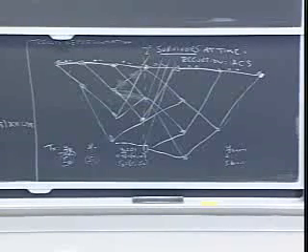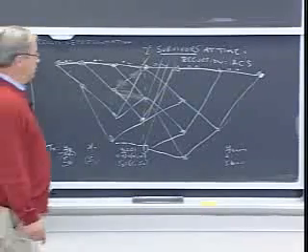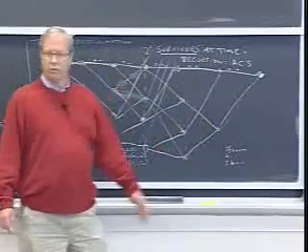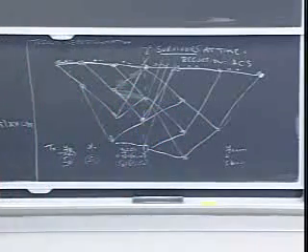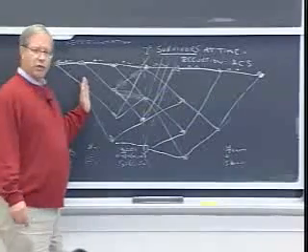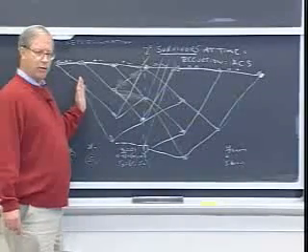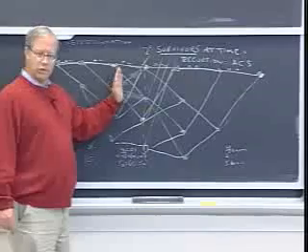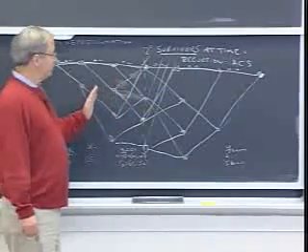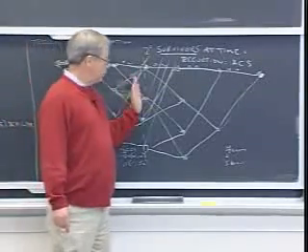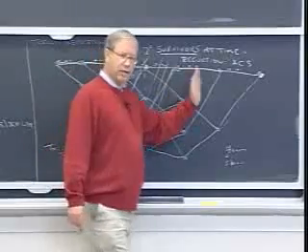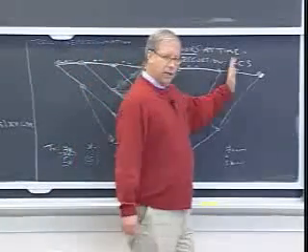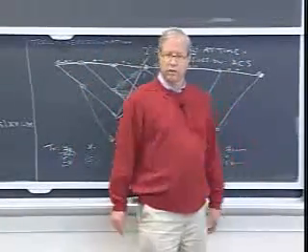I believe it's just totally obvious once you reduce it to a search for a minimum cost path through the trellis. It's very well suited to the application of convolutional codes because we really are thinking of sending these bits as a stream in time. And at the receiver, you can think of just proceeding forward 1 unit of time, doing 2 to the nu add, compare, selects, and we've got a new set of survivors.